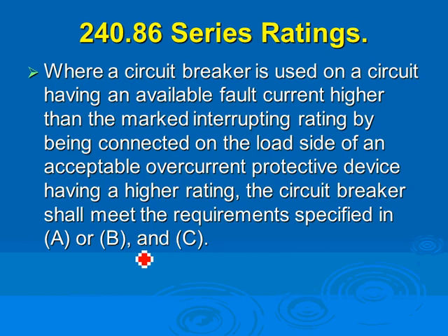If you have a breaker rated 240/120, can you put it in a delta system? That's another application for circuit breakers. If your circuit breaker says 240/120, you can't install it in a delta corner-grounded or ungrounded circuit, because if you ground the delta, the voltage to ground would be what? 240. And if you have a 240/120 breaker, the voltage to ground rating is what? 120. So you exceed the voltage to ground rating of the circuit breaker. That's a major thing when it comes to circuit breakers.